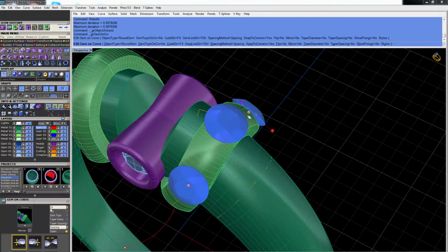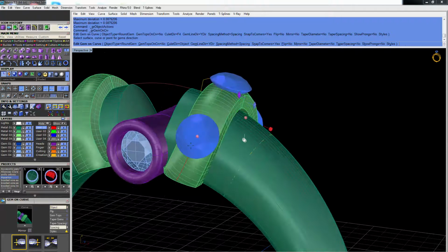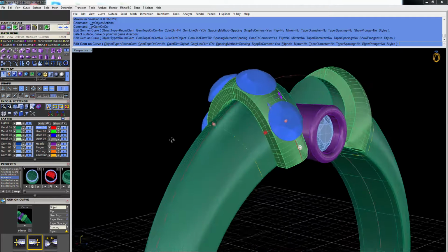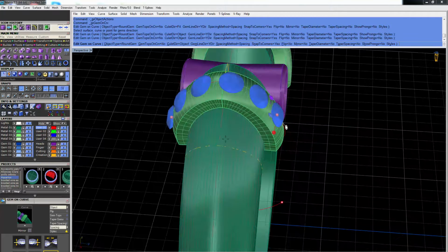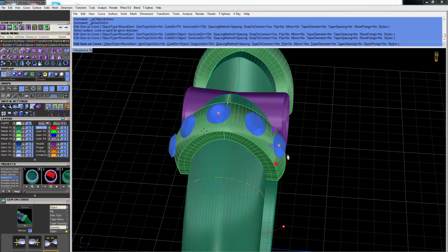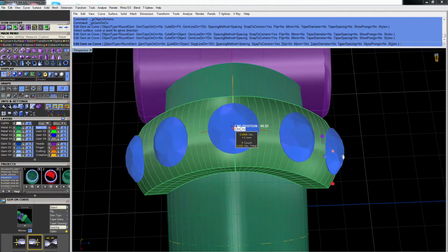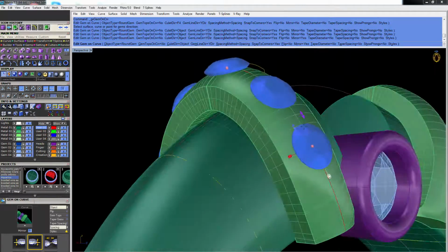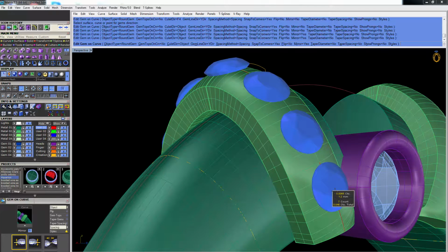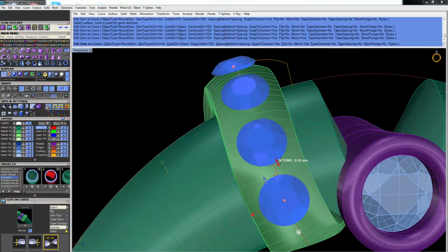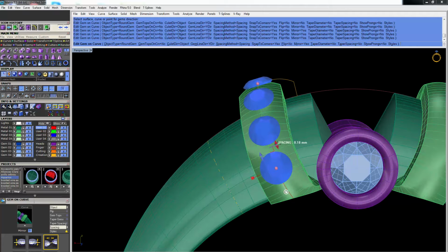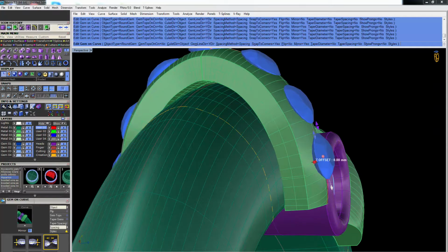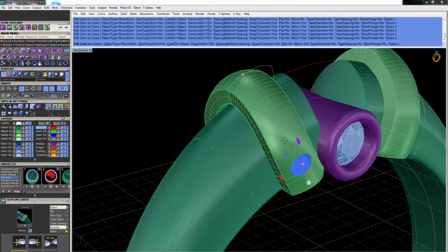Gem and curve, instead of F4, instead of down, click on object. So now all the gems will be looking at the object. Okay, we must make them smaller, and in this case, as it's something mirrored, we should check mirror and make sure that dot stays here in the middle. So now everything is mirrored. Okay, let's pull them down. Also just play with spacing a little bit. Yeah, well, let's leave it like that. I mean, this is just to show you how it's done. It's not like a final product. Okay, always make sure to bring them inside a little bit, maybe not that much.